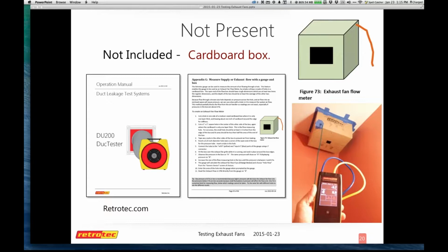And we'll talk about how the tubing gets connected in order to read your measurements. But right here I'm measuring the pressure on the blue tube on channel A, and channel B on the yellow is reading the actual flow that moves through the box. So it's a very accurate system that you can use. You just want to make sure that your pressure tube is not directly in the flow. It's off to the side, and it's as accurate as any other device that I've used for challenge purposes.